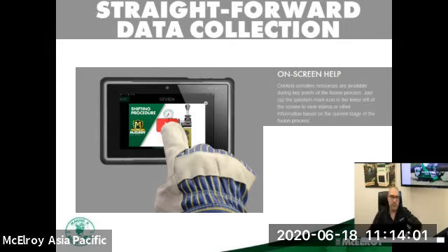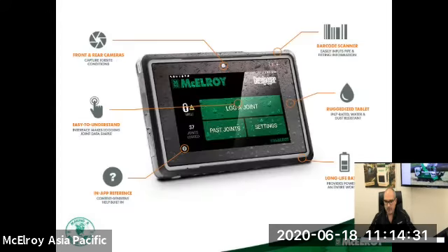For example, if the operator can't remember exactly how to do a shift sequence, just clicking on the question mark for that step, it'll show you a video on, okay, you have to move the selector valve to heating, and then the directional valve neutral, so providing very useful help for the operator.